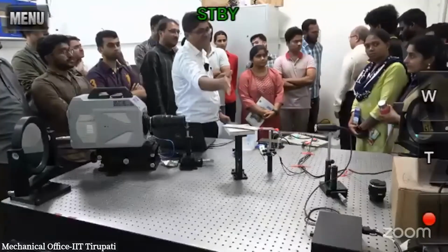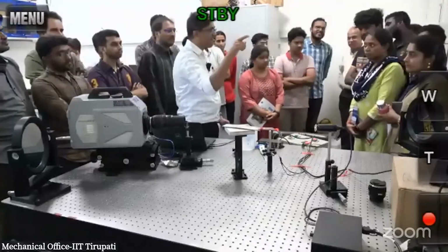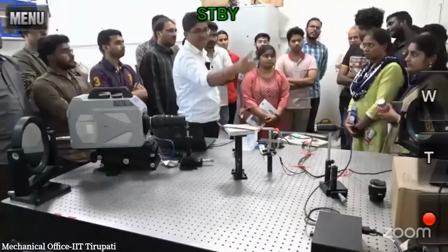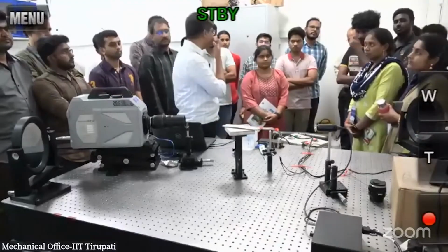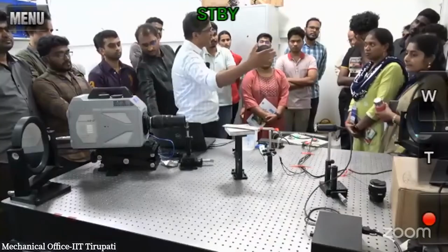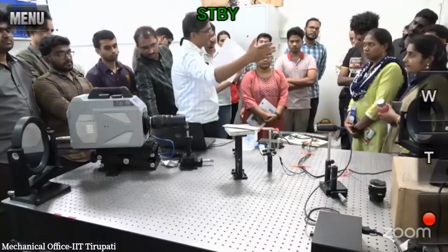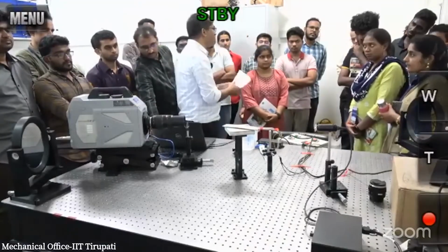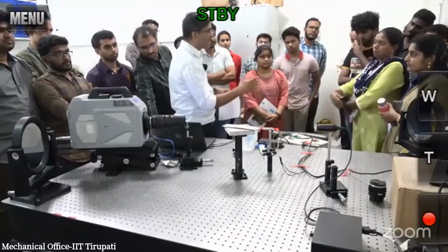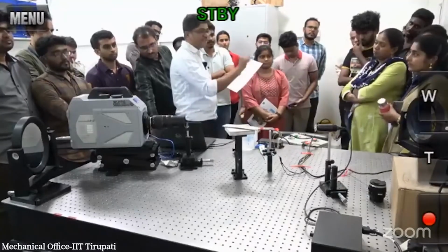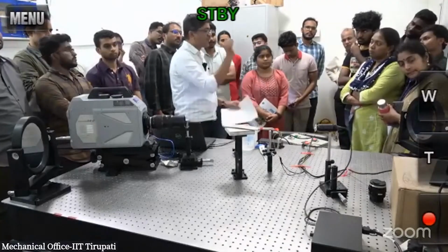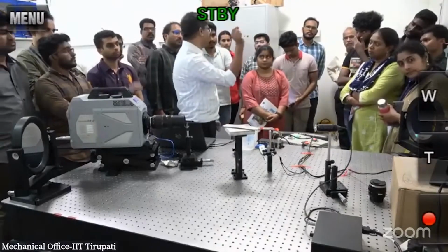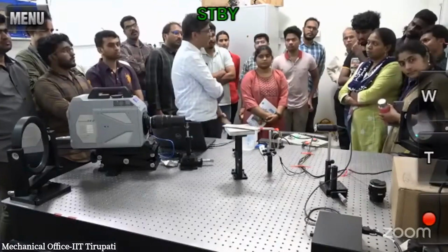I put a scale, then you know the length. Let's say we are capturing 10 centimeters, so 100 millimeters is captured in 1,000 pixels. Then the calibration will be 0.1 millimeter per pixel. If there is a drop, we can measure its diameter in pixels and calibrate to get that.